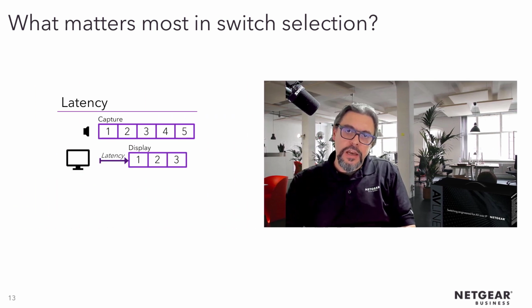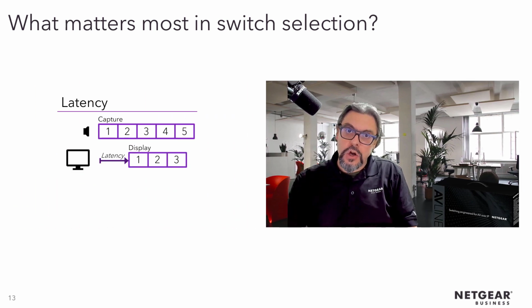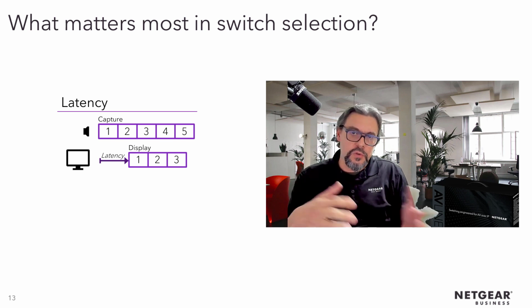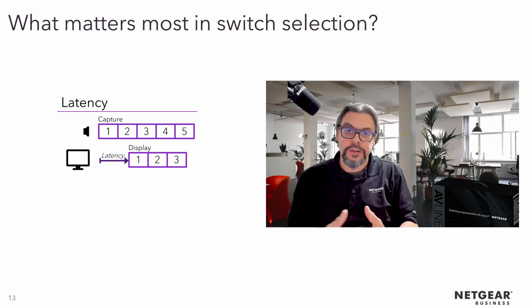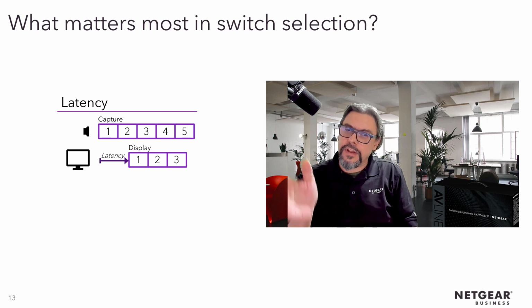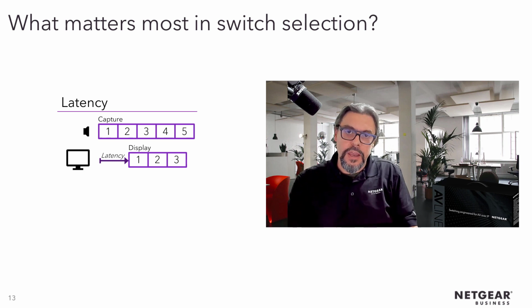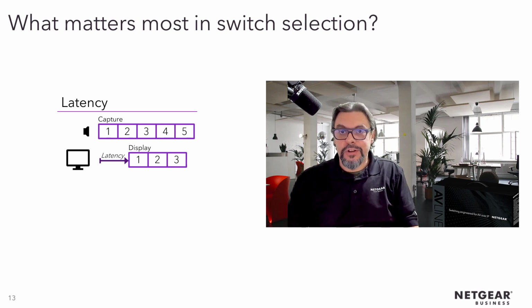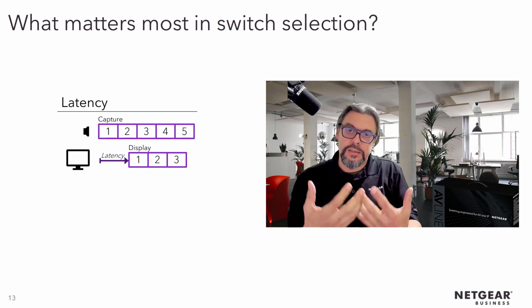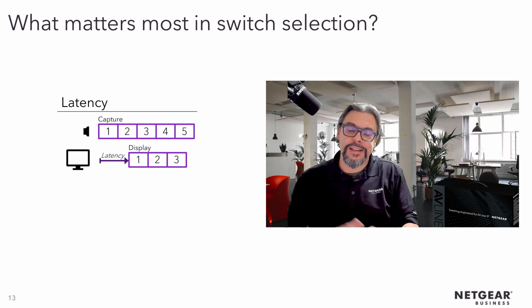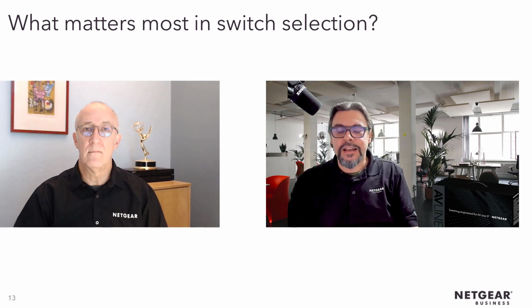Now let me get back quickly to the latency. Why doesn't it matter? Because for you in the AV industry, latency is measured in milliseconds, right? But the switchers, good switchers, bad switchers, all Ethernet switches in the world, they measure that in microseconds. So that's totally irrelevant for AV over IP, because switches will never add any latency to your AV over IP. And for codecs, that's pretty much the same thing. All that to us is packetized into packets. There's no good packets or bad packets. They are simply packets that we forward as fast as possible.